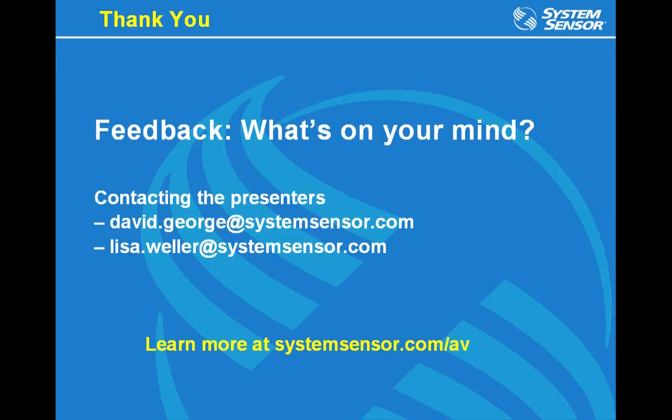Okay, all right. This question deals with your ADS comments. Are there any intelligibility requirements for outdoor ADS environments? No, they're not. When you're outside, there are no considered acoustically distinguishable spaces, and you also can't run intelligibility testing outdoors because the sound is moving in a much wider area, so being able to test for intelligibility in outdoor applications would not be possible.